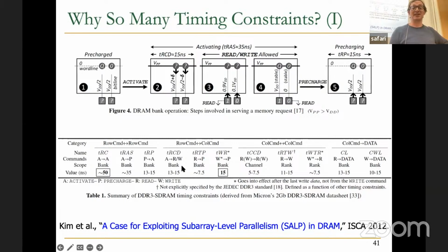Let's see, what should I pick? tWR. After doing a write, you need to do a precharge. I need to wait for some time so that the data is actually guaranteed to be written, including the guard band that's added. In this particular case, it's 15 nanoseconds, for example.